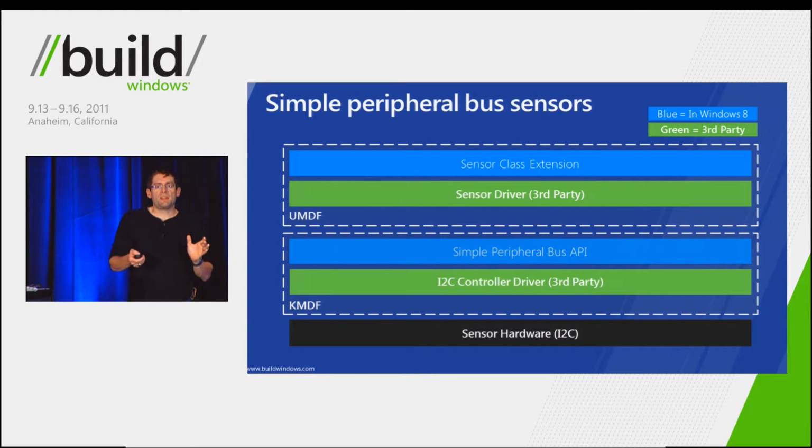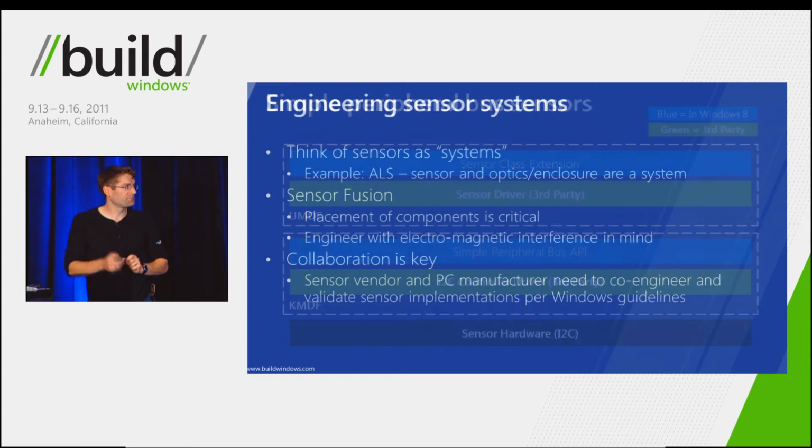So the great news here is the middle green box there, the sensor driver third party, is really all that you need to do from a software perspective. The I2C controller driver will be there for you, and then you can very seamlessly support your simple peripheral bus sensors.